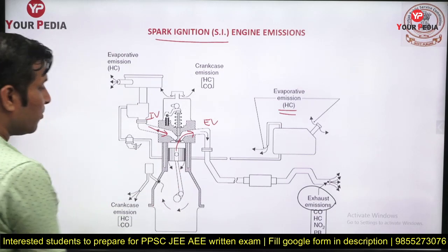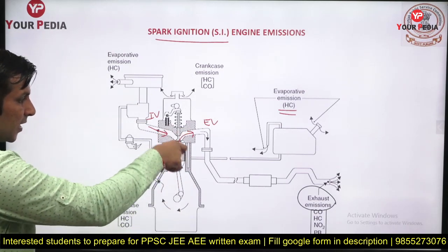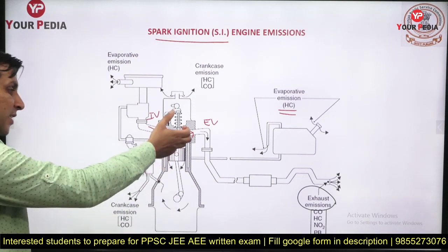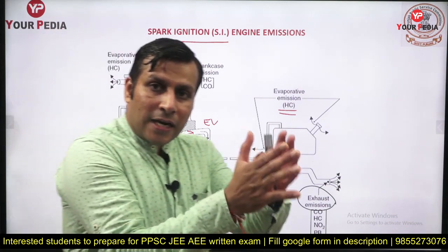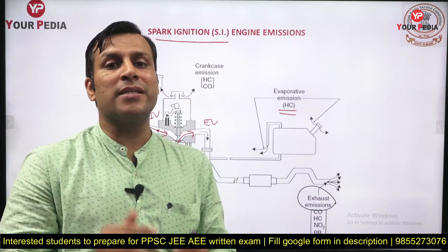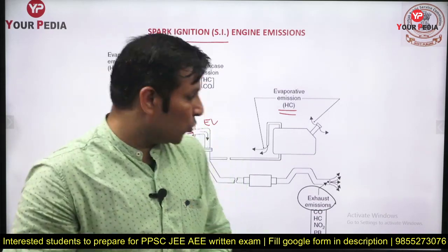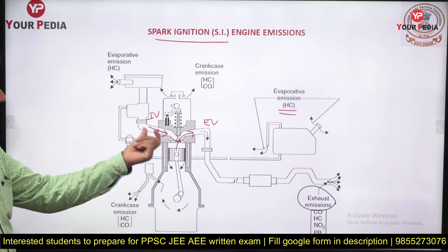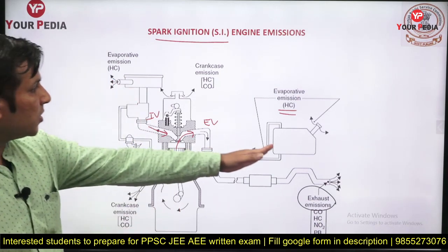This is known as engine blow-by, guys, because these gases, hydrocarbons and other exhaust gases, are leaking into the crankcase. That is known as engine blow-by. It is a kind of loss. Fine. So engine crankcase, the losses in the intake manifold, the losses in the tank.